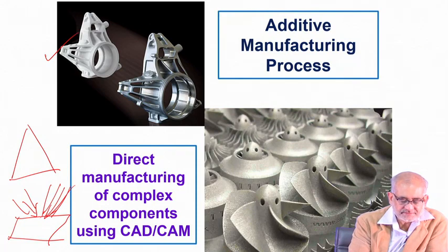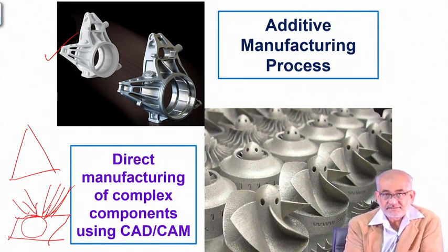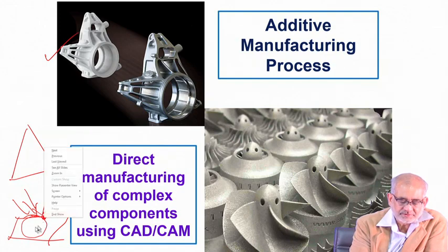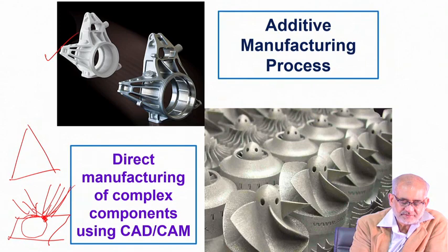So in the first case, I'll allow a circular motion of the beam or the stage, in this case maybe the beam, and the powder hopper. So the beam interacts here and the powder comes and hits here. So you melt the powder and you deposit the molten powder at this point. And then the beam and the powder move away, and they go to the next spot and again deposit another layer. So likewise, if I make a circular motion, then I'll create one circular section like this